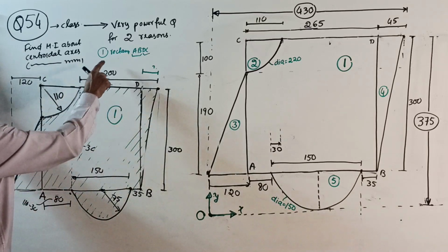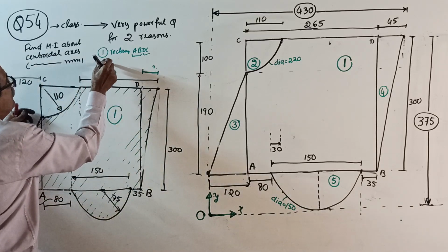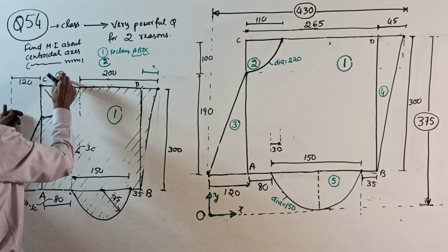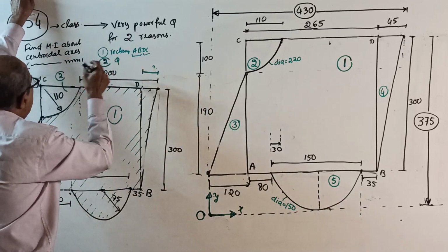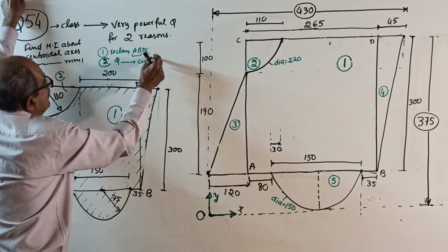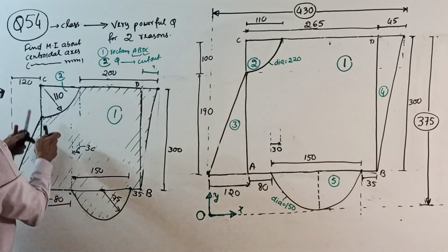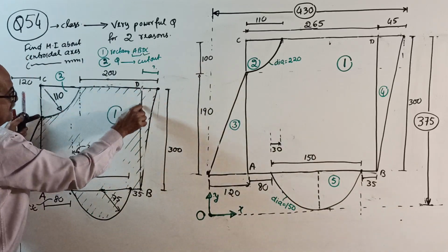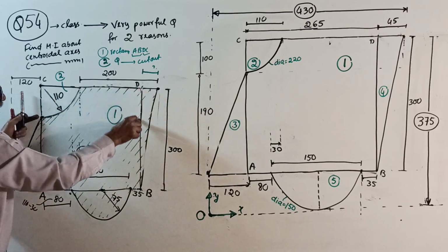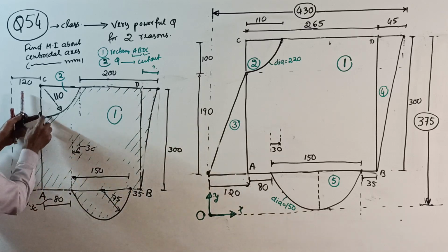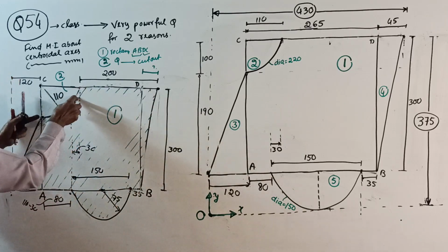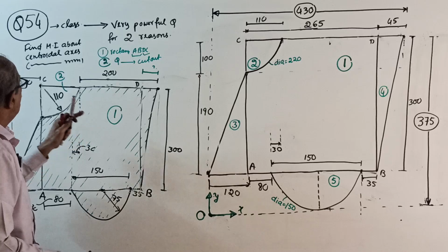See, now this is not there. So actually, one rectangle. 2, I will take this one. This I will take 2. It's a quadrant, right here. It's a quadrant of a circle, whereas this 2 will become cut out. Because, see, actually the area is here, but we are taking this much. So the real existing area in the rectangle portion is this area minus this area. So 2, I will remove.